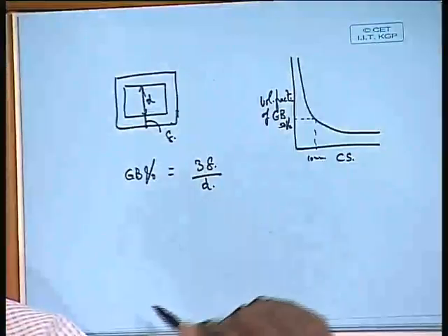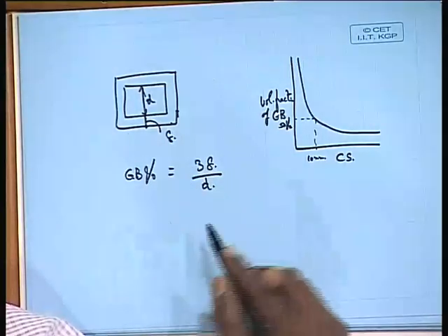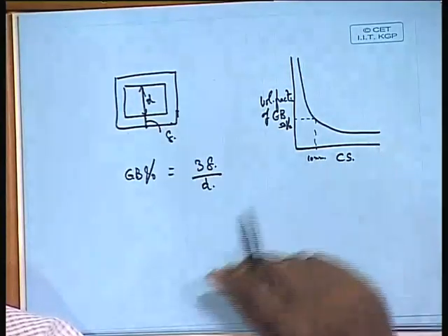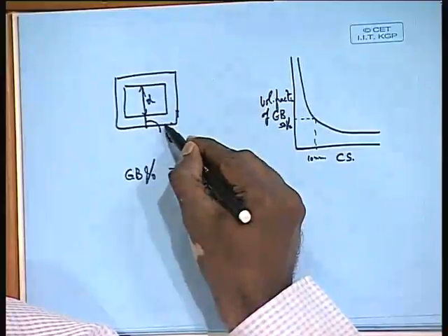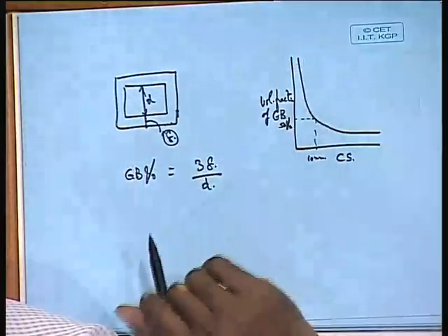If we use about 10 nanometers, you reach for a grain boundary thickness of the order of around 1 nanometer. Usually grain boundaries have a thickness of about 1 nanometer. Okay. In principle, one has to also consider that as you decrease the grain size, the grain boundary thickness itself keeps on changing, and it keeps on increasing when you decrease the grain size below around 10 nanometers or so. Beyond about 50 nanometers, the grain boundary thickness does not change that much, but if you go to really very small grain sizes, the grain boundary thickness will also be larger, and as a result this delta is not a fixed number, but for all practical applications usually people assume the delta to be around 1 nanometer.